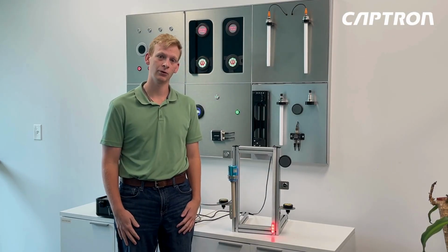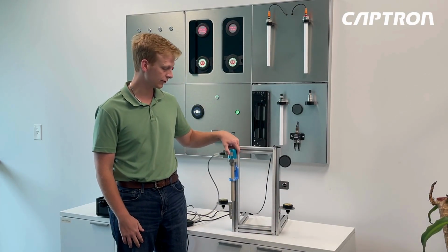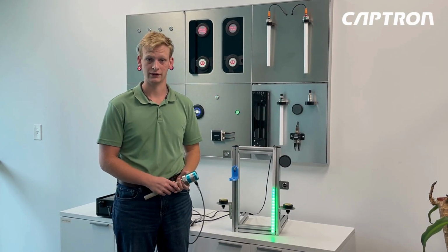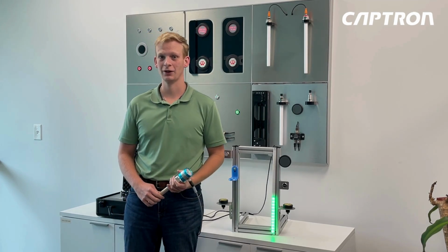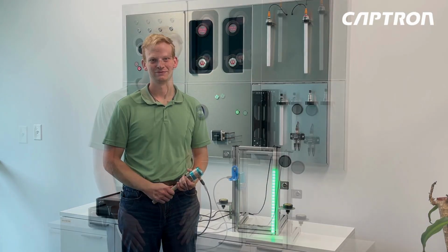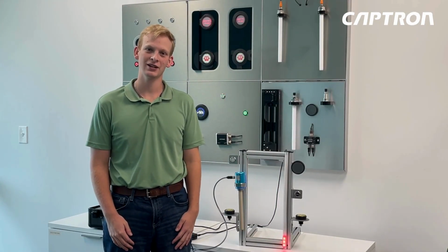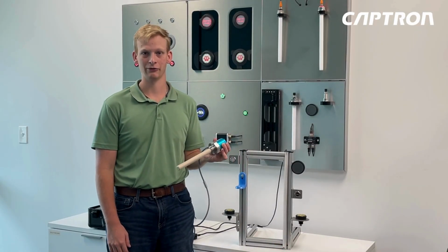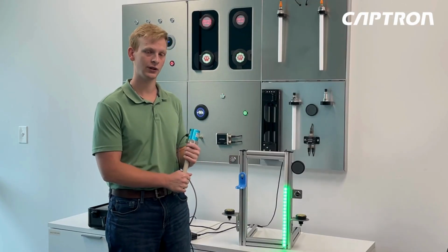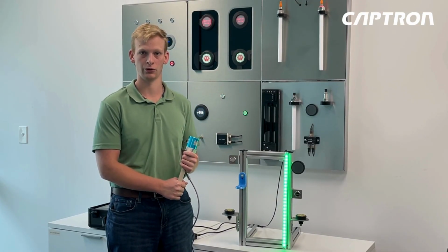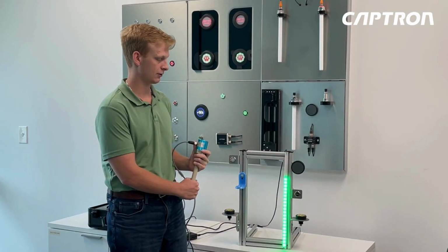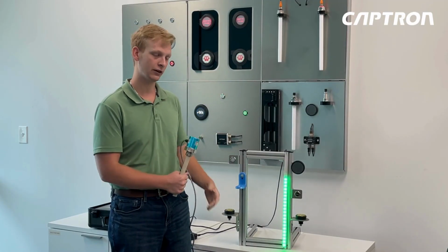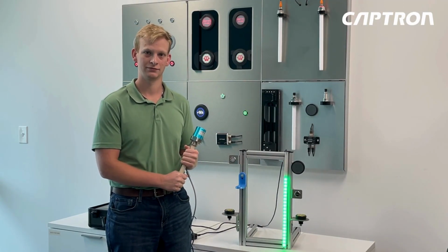And for this example, I have one of our level sensors and our LED strips running on our MQTT controller, where it is then hooked up to a PLC. And what we're doing today is showing off our LED strips with our capacitive level measurement device using an MQTT controller and PLC. So as you can see right here, as the level increases in your tank, the LED strips signal that.